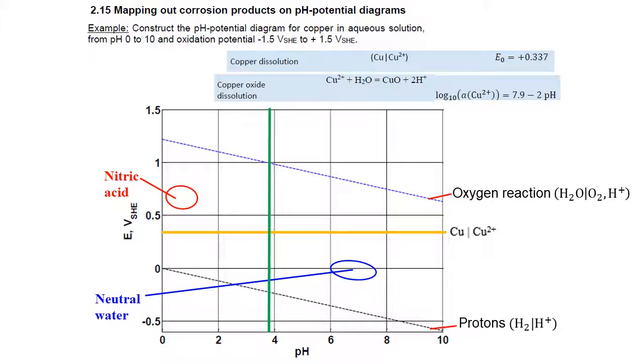And by more stable, we're considering a system, this is the equilibrium line for 1 molar copper 2+ ions. So more acid than pH 3.95, if I have currently 1 molar copper 2+ ions in solution, I expect there to be dissolution, so more copper 2 oxide will dissolve. Okay, so taken together, this means in the top left of the diagram I have a region where copper 2+ dissolved ions are the most stable phase. They're more stable than the metal, and they're more stable than the solid oxide.